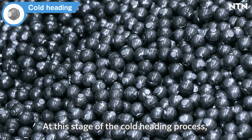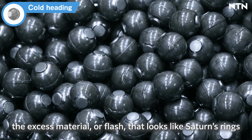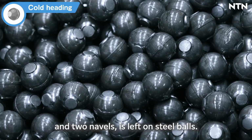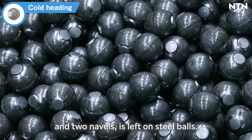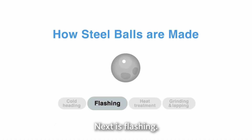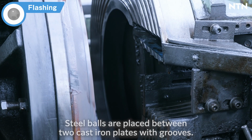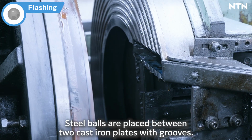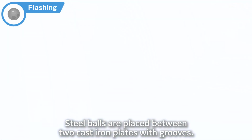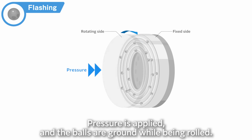At this stage of the cold heading process, the excess material, or flash, that looks like Saturn's rings and two navels is left on steel balls. Next is flashing. Here, the flash left from the cold heading process is removed. Steel balls are placed between two cast iron plates with grooves. Pressure is applied and the balls are ground while being rolled.